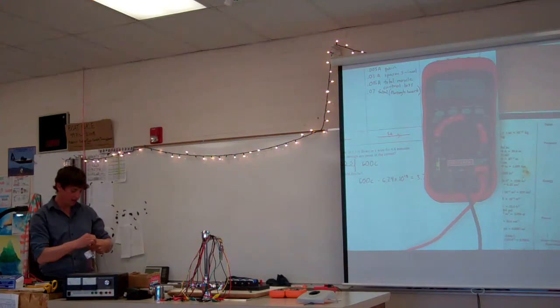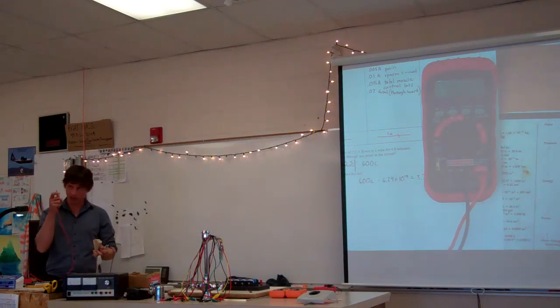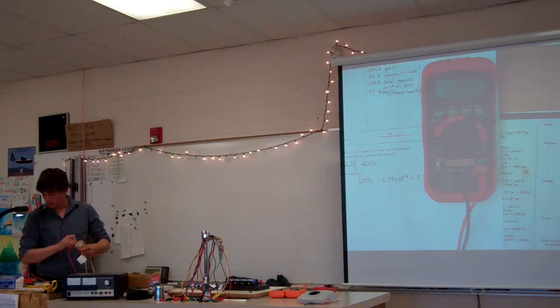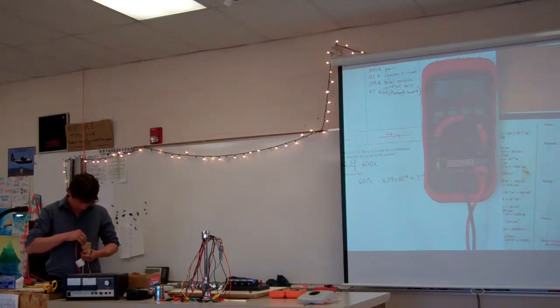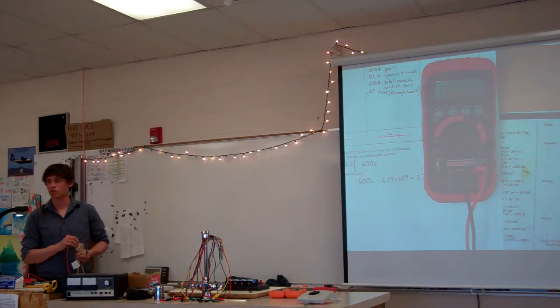Okay, now if I connect this here, okay, that's the ground portion of the wire, and then I take this and connect it right here. You can see it instantly is trying to read the resistance, okay, and I'm not getting a good connection. How come it's bouncing from such high numbers to such low numbers? Well, because I haven't connected it solid yet. Okay, so there we go. Now it'll kind of stabilize. It'll kind of fluctuate for a minute. Stabilizes on 2.4 ohms. Okay, that's an extension cord, 2.4 ohms.